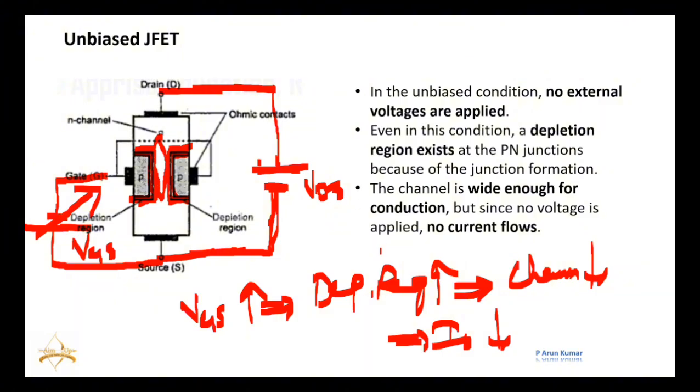So that is why the drain current will decrease. It means internal resistance is increasing. So that is the connection we can give here. Here we had a VGS in negative and VDS is positive. In this way, we are controlling. Actually, by giving this VGS in negative, we are controlling the charge carriers. We are decreasing the charge carriers. Somehow, increment or decrement, we are trying to control the charge carriers, right? So we are controlling these charge carriers by giving a reverse bias at the gate terminal.